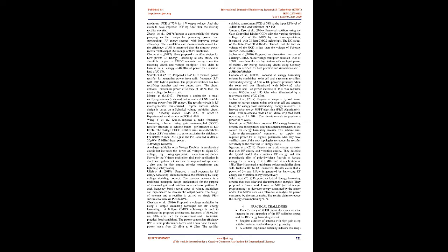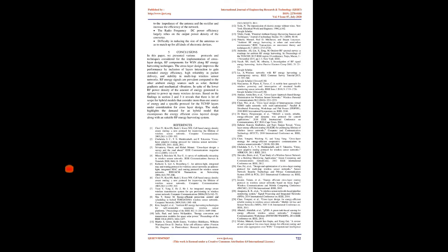Chen et al., 2013, proposed a rectifier that uses a multi-band impedance matching circuit with Villard structure, a low-pass filter, LPF, to suppress wideband harmonics and a load terminator. The circuit receives in-band signals and cuts off the out-of-band signals so as to effectively block the backscattered nonlinear frequency components from the nonlinear rectifying diodes to the antenna. The fabricated scheme results in high conversion efficiency.